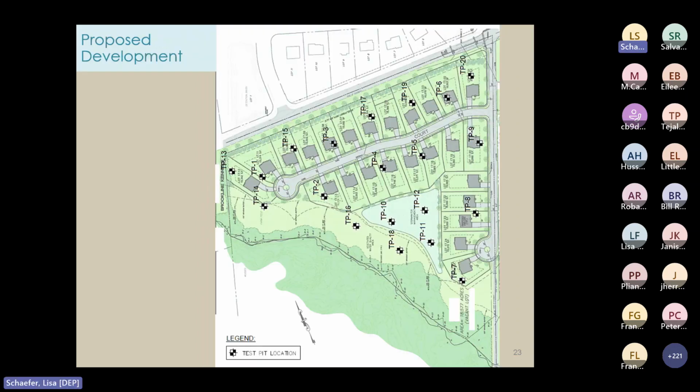So first, let's look at the soil exploration map, which indicates quite a number of test pits were completed, although at the time that this plan was prepared, only one central basin was anticipated, where I've indicated here. So perhaps a preliminary concept predated the amendments to the stormwater management rules. Now, as you know, major development projects are required to use GI BMPs, and they're smaller in scale, and they treat stormwater runoff close to its source. So it's good that the designers realized the single basin approach wasn't compliant and went with multiple BMPs.